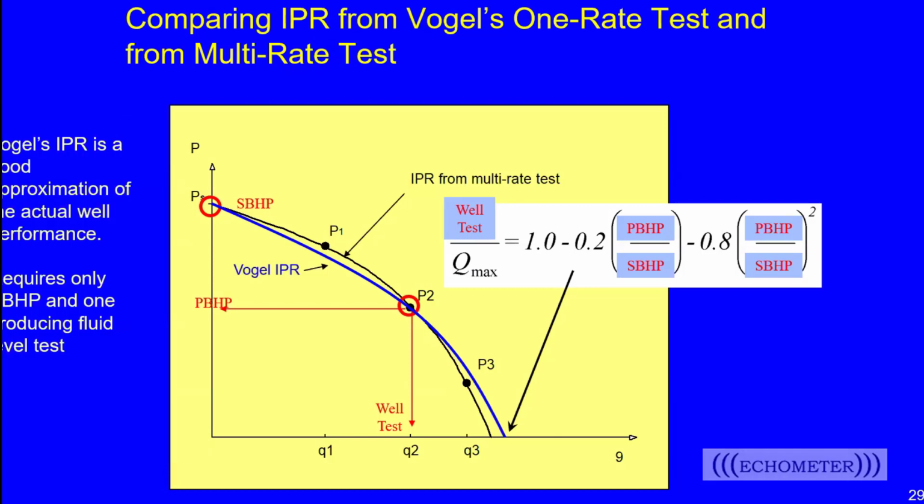One advantage of having a rod pump well is that if you have a good dynamometer measurement and you do a detailed analysis of the pump dynamometer, from the pump dynamometer you can establish an accurate flow rate that the well is producing. And I think there will be a presentation on that subject coming up in the future. So you may want to make sure that you don't miss that one.